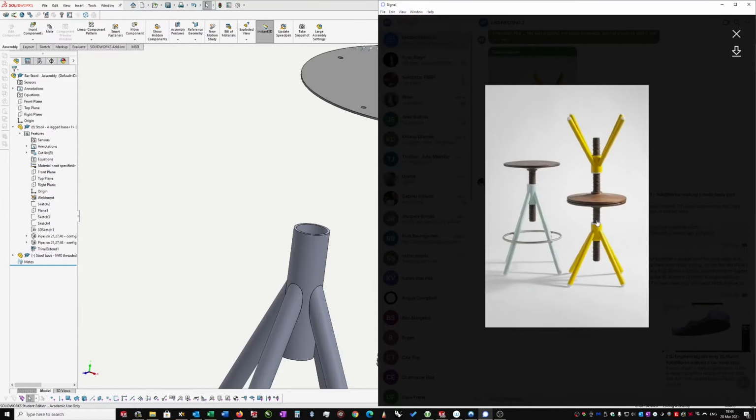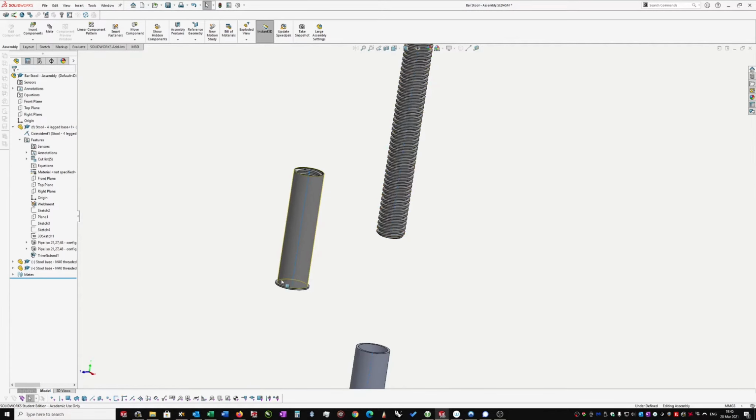Browse, it'll go straight to the folder which I've been using, and here it is. I've called it a flange insert. Okay, so it's got a reciprocal thread. I need to turn that around, so I'm just going to right click, drag, something like that. I mean, just to show you, I could leave it like this and I can still align these two pieces by holding the Shift or the Control button down, and that should give you a range of alignments at the bottom, or mates.